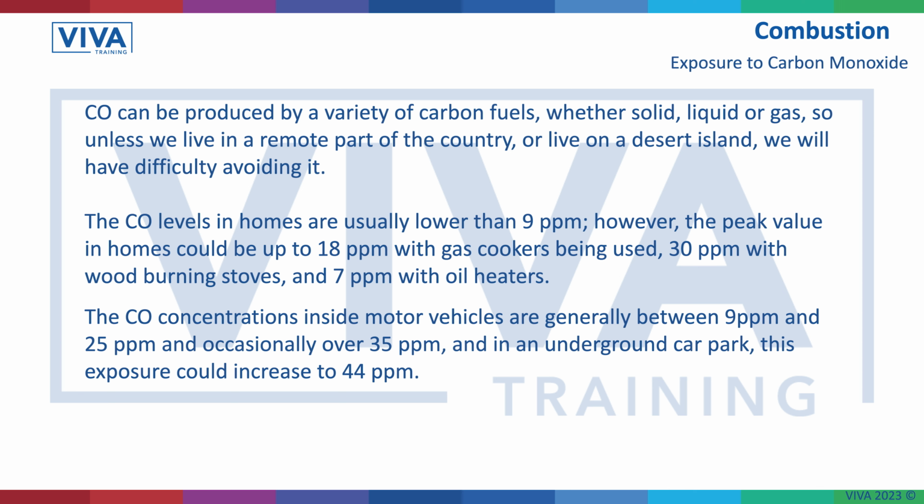There's 2 ways that carbon monoxide can cause you harm. One is long-term exposure to low levels. So for instance, a gas appliance, let's say a gas fire, is producing carbon monoxide and the customer's sitting in front of it on a winter's day for 3 or 4 hours a day. That carbon monoxide's going into their body and it's sticking to the blood and stopping them getting the oxygen into the blood. And that could take weeks before they start to feel any effects from it.